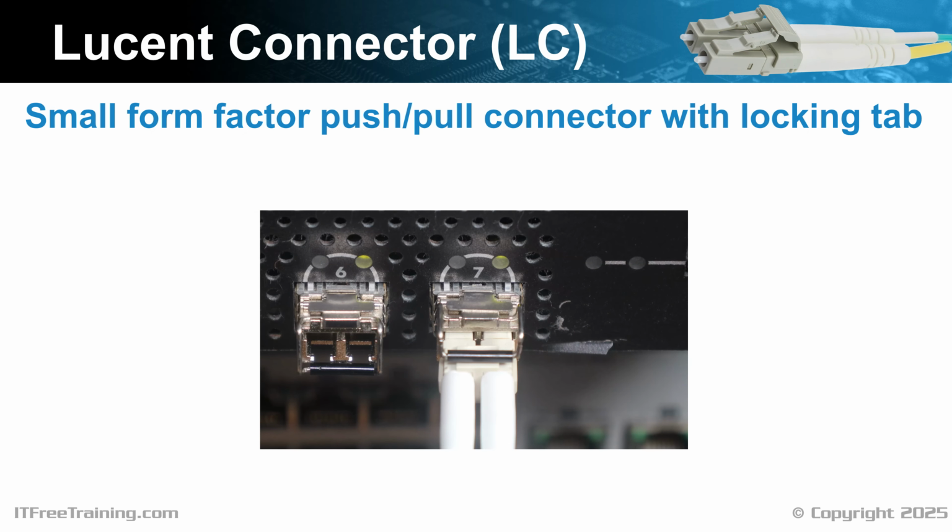The next connector I will look at is the Lucent connector, commonly referred to as the LC connector. This is a small form factor push-pull design connector with a locking tab. All you need to do is push it in and it will lock in place. The LC connector comes in both single and dual configurations. However, the dual connector variant tends to be more prevalent with patch cables.